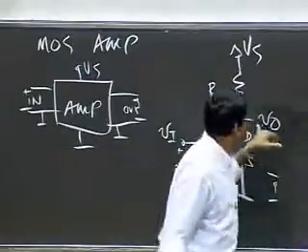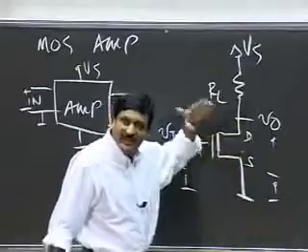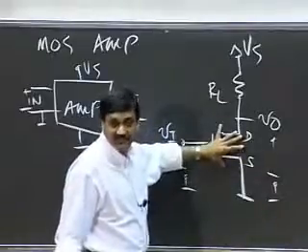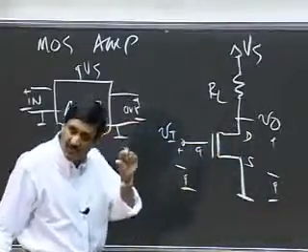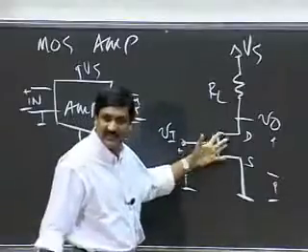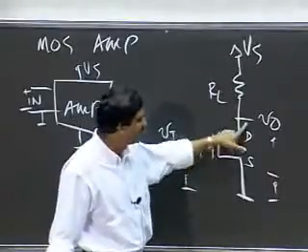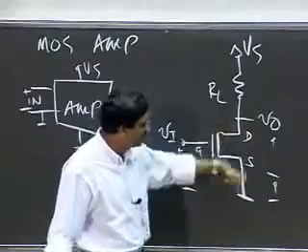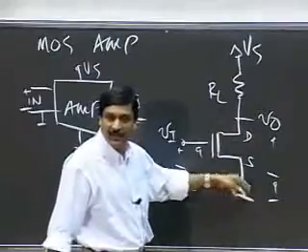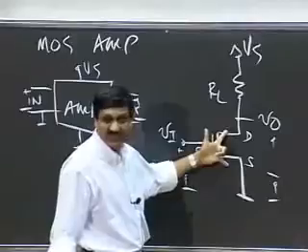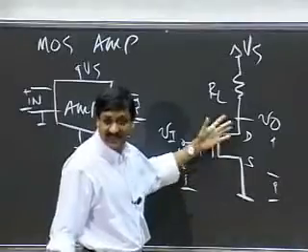In other words, when VDS is greater than some value, then this behaves like a current source. When VDS is small, as in the digital designs, where the MOSFET when on pulled the voltage down to ground, we could view this behavior as a resistor. It is actually the same thing.